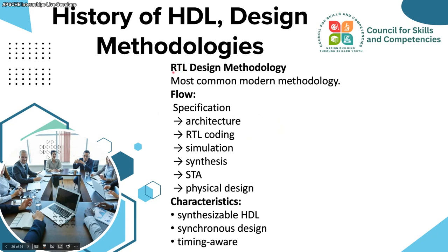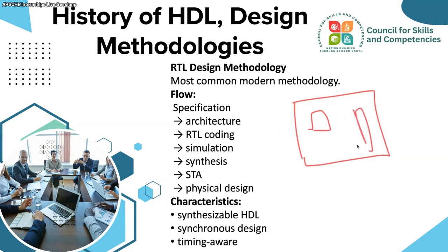Now, RTL design methodologies, this is the most common modern methodology we try to use. Okay, the flow is architecture level, where we tell this is what I need. For example, the CPU only does load and store, all the operations happen over here, and only for storing it will come to the memory.